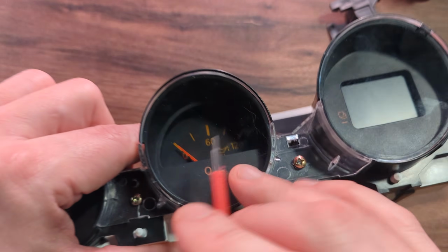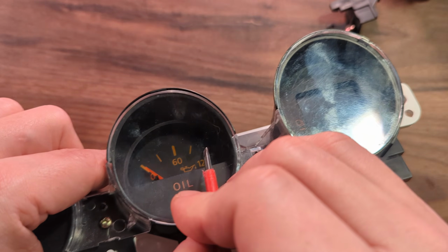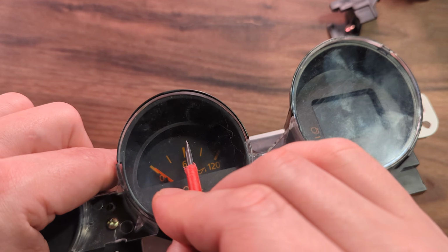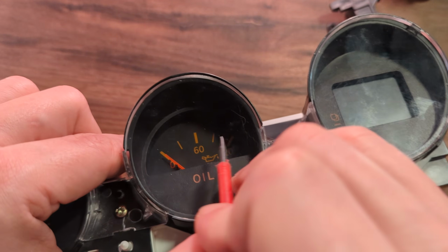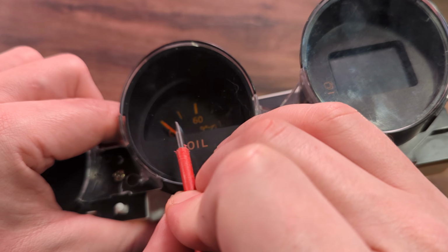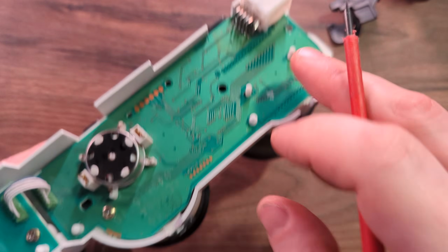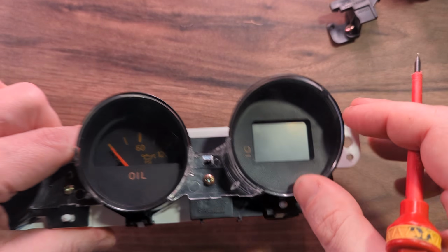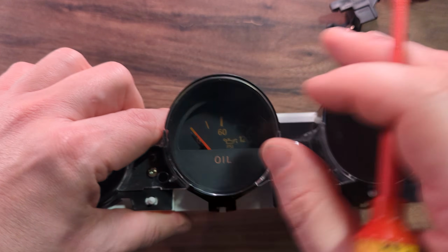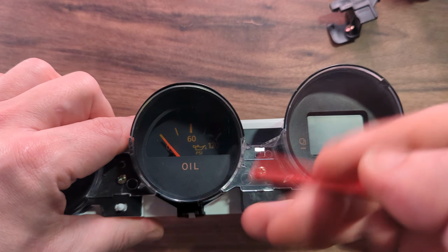And then whilst I'm doing that, refer to the oil pressure here and see what voltage we're getting at each oil pressure. Now, it's going to start high when I turn the car on, somewhere between 90 and 120, and then slowly reduce as the engine warms up. So I'm going to try and capture it at 90, 60, and 30 psi, because if I can get it at those 3 and see what the voltage is at those 3 values, then we can use that to create a formula which will roughly tell us what the conversion rate from voltages to psi is.